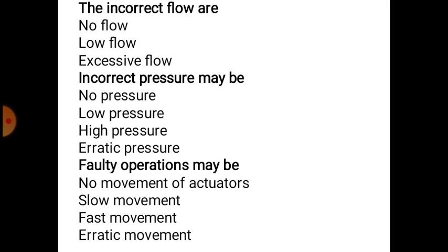High pressure. In this case the pressure of fluid is much greater than required. The reason may be improper adjustment of pressure valves, or worn out or damaged valves. Remedy: adjust or replace the valves. You must adjust the valves or you must replace the valves.